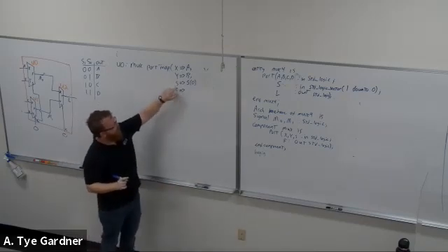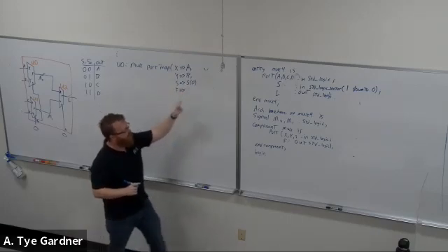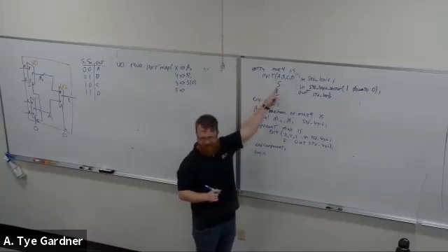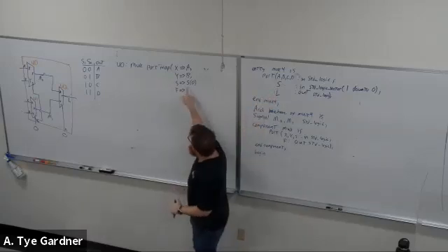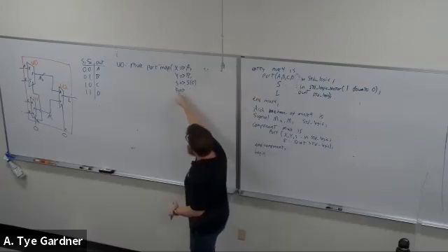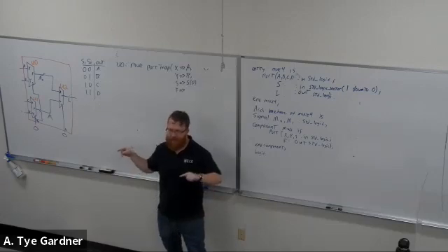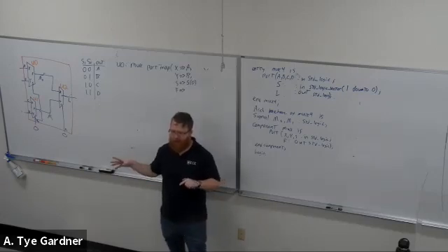See how this S and that S are the same letter, but they're different ports, right? This S refers to that S, and the S at 0 refers to that S, and this S is the port that's inside the mux. So this is kind of bad. I wanted to show you why you need to be careful with your port names.